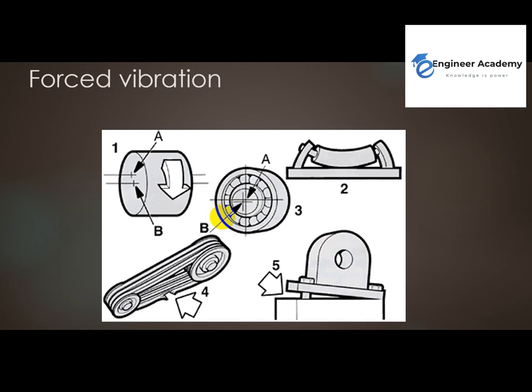Any part in the bearing could fail, producing vibration also, making the body vibrate. Bent shaft, cutting belt, looseness, all of this can make vibration. That's why it's important for me to measure the vibration and make this analysis to figure out what the source of the problem is. Does it come from unbalance, from bearing, from bent shaft, from looseness, from anything?